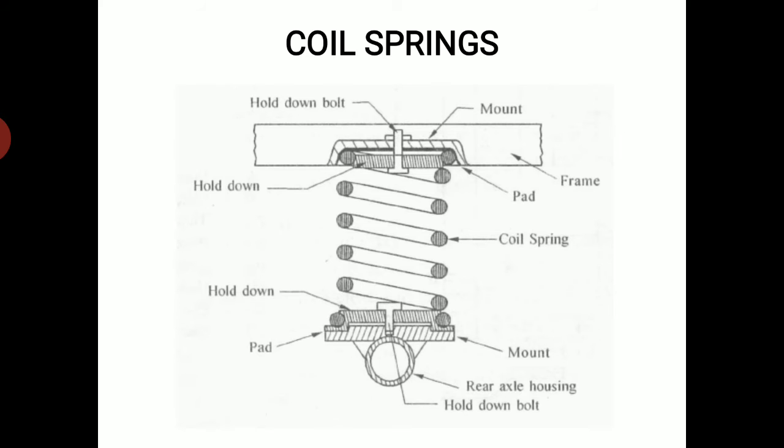Then the rear axle bearing. Nowadays, coil springs have become very popular because of the limitations involved in leaf springs. The figure shows a front suspension system using coil springs. In the figure shown, the coil spring is held between a spring seat in the car frame and a lower control arm. The inner ends of the control arms are attached to the car frame.